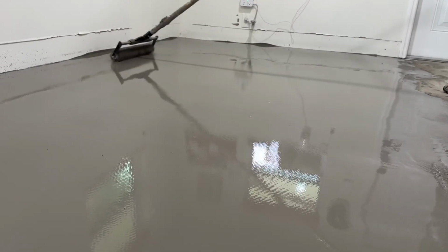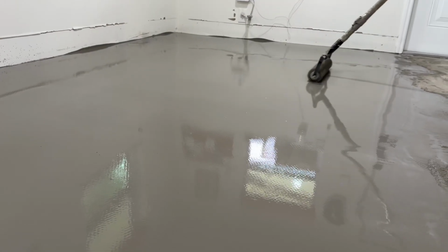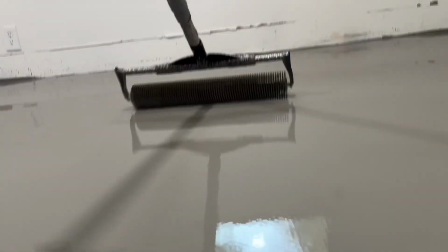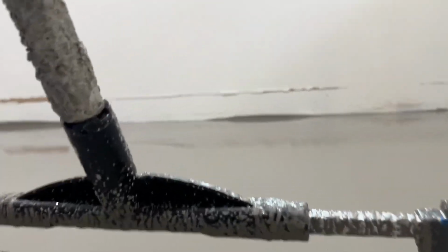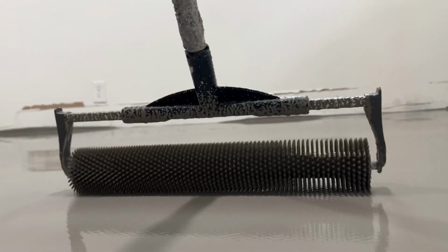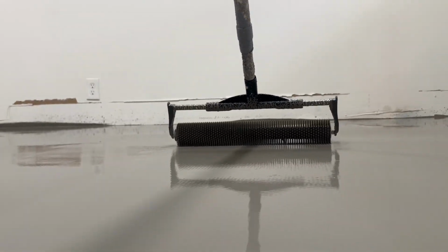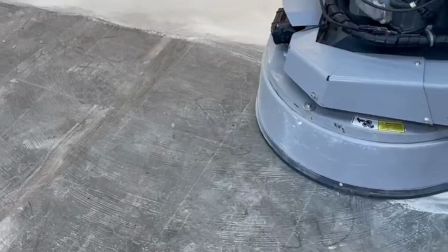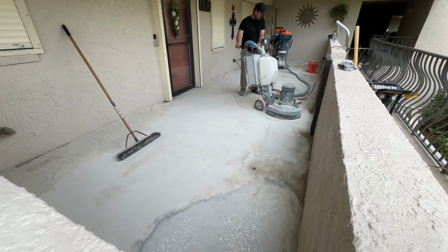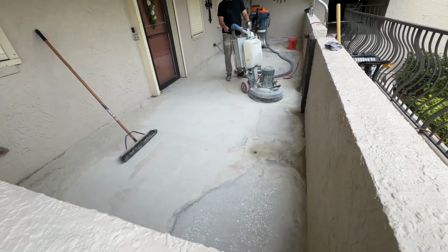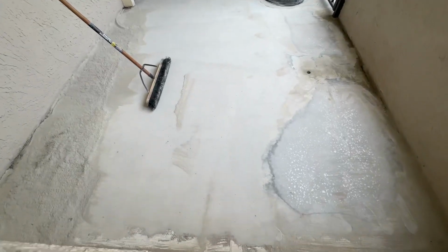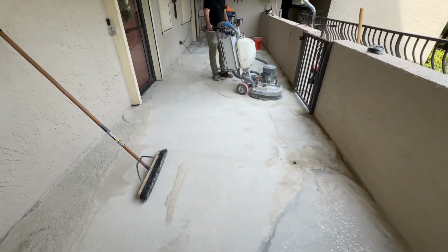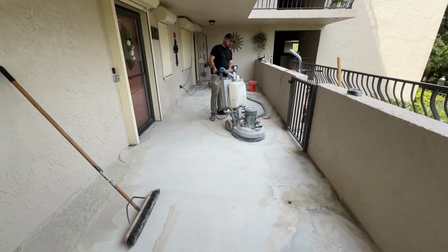You want to start off with the proper surface preparation, and that's cleaning the surface. Before applying any coatings, ensure the concrete surface is clean and free from dust, dirt, oil, and other contaminants. We achieve this through the grinding process. Then we'll fill any voids or irregularities in the concrete. We use cementitious patch products to create a smoother surface and reduce the potential for outgassing.